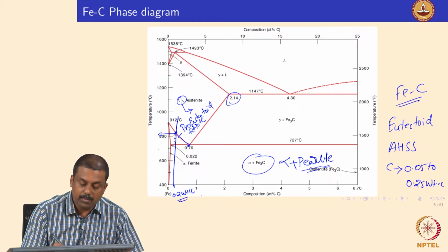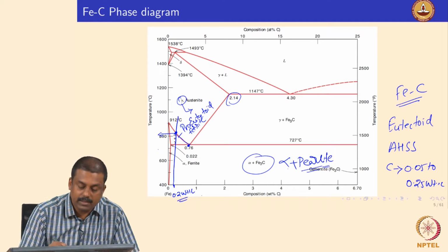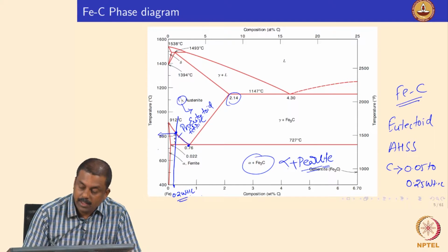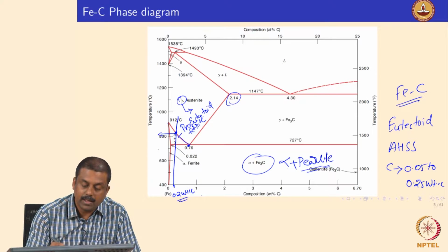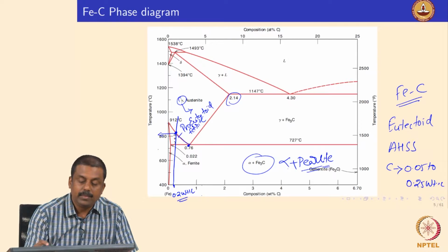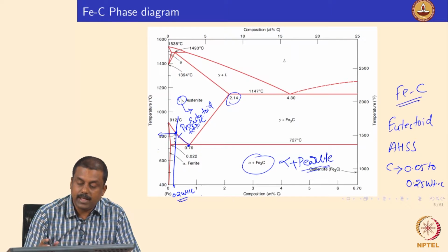And subsequently, the moment the carbon concentration of austenite reaches the eutectoid carbon concentration, the remaining austenite would transform into pearlite. Okay. So, if you are cooling steel containing 0.2 weight% carbon, you may have a mixture of pro-eutectoid ferrite and pearlite, right. So, now this diagram does not tell you about the time.